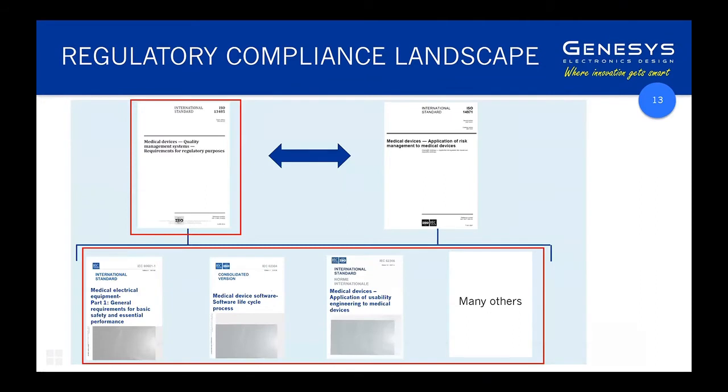Will do. So having a look at the standards, old friends, the headline standards with ISO 13485 and ISO 14971 as the headline, and then the applicable regulatory standards for the device that sit under that, and the fairly universal ones that will apply to any active medical device. 60601-1 for anything that's electrically powered, 62304 for anything that's got software in it, 62366 for usability, which applies universally, and many others, including things like cleanliness, sterilization, biocompatibility.